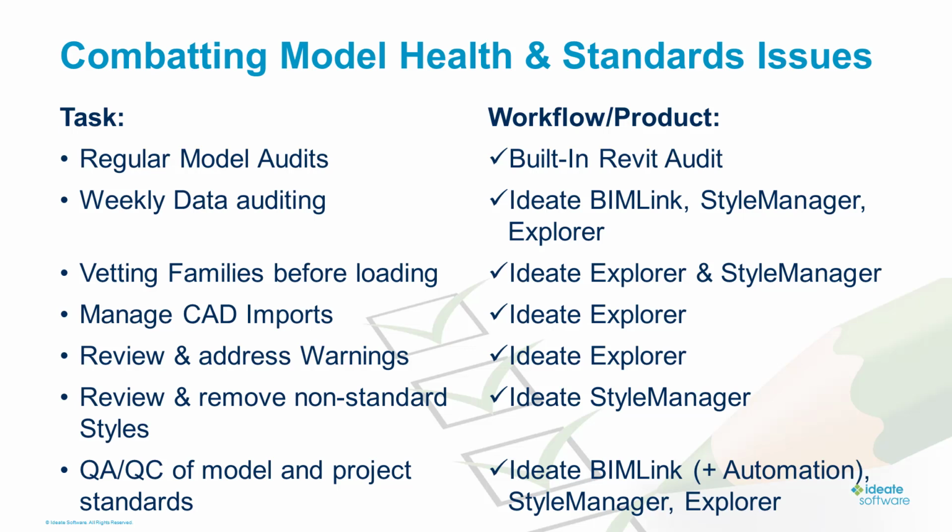CAD imports, definitely Explorer to just get that stuff out of there. You can use BIMLink again to report on CAD imports, so you can go back and say, team, use Ideate Explorer to clean this up. Great way to use that health check template that I showed you earlier to come back and say, we need to use Explorer to fix these kinds of things. And of course, for general QA QC, BIMLink with automation, depending on how many you have, Style Manager and Explorer. These products will help you clean this up.